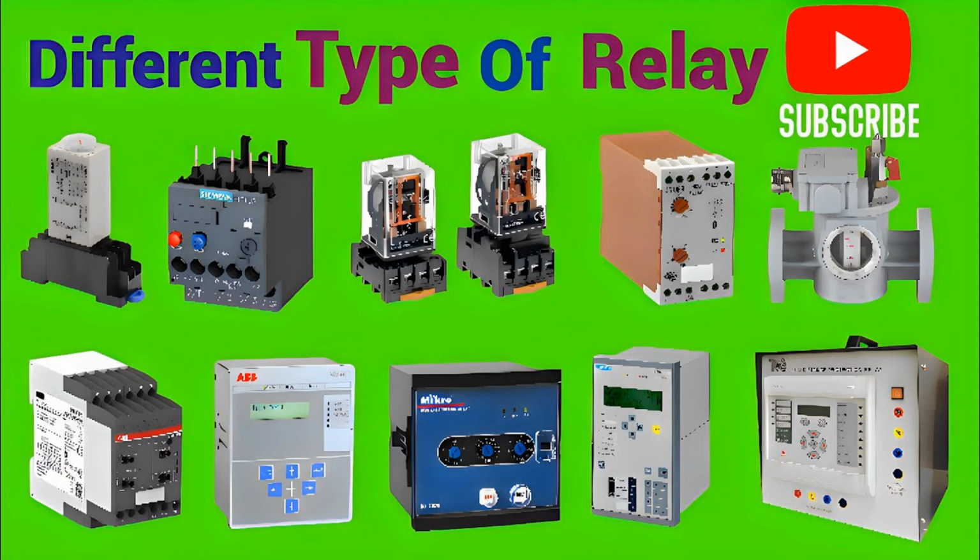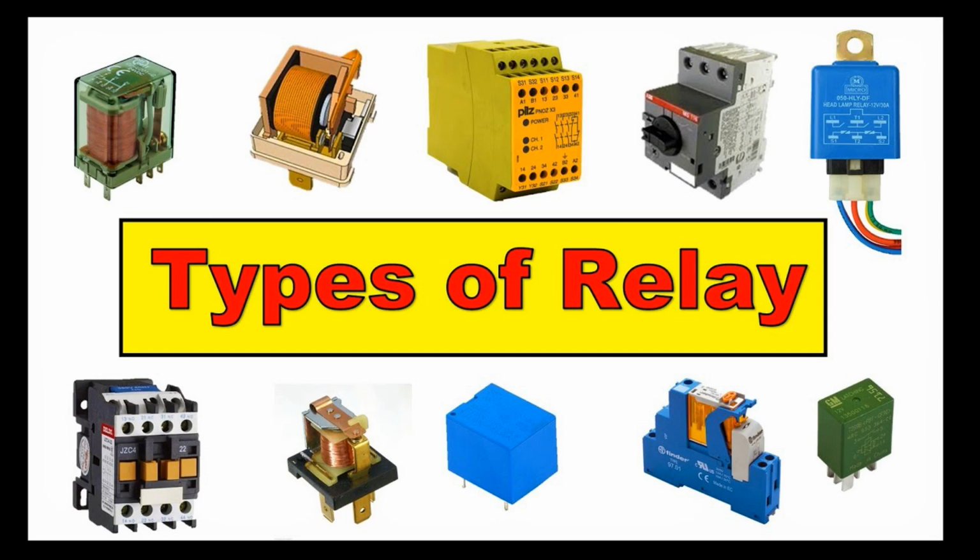Working principle. Set operation. When a pulse of current flows through the set coil, it generates a magnetic field, moving the contacts to the latched position. Latching. The latching mechanism holds the contacts in this position after the set coil is de-energized. Reset operation. A pulse to the reset coil generates a magnetic field in the opposite direction, which moves the contacts back to their original position.